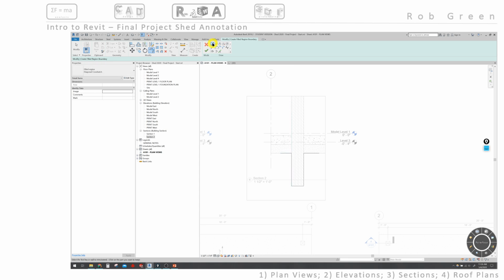And what I want to highlight is that when I'm drawing lines, I have the option to define the line style. And here I've chosen thin. So now I want to draw some just kind of jagged lines around this edge, but quite frankly, I don't want to see the outside boundary of those lines. And when I do that, I have the option to choose to draw invisible lines. So that's what I'm going to do.